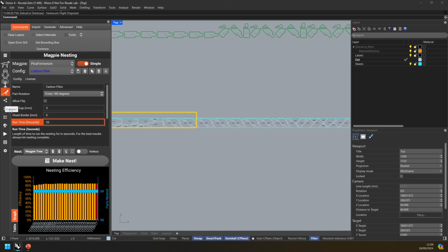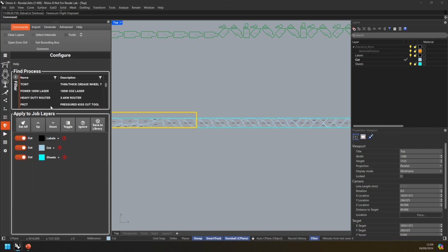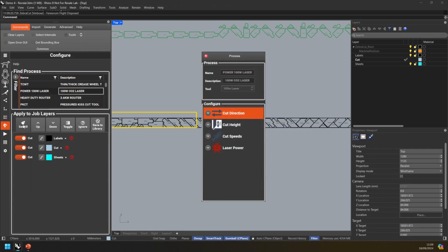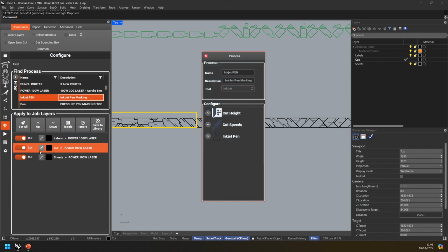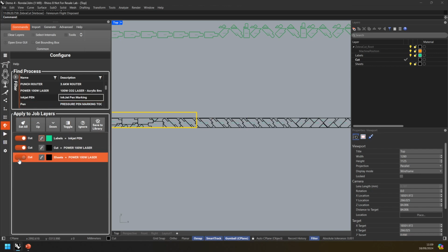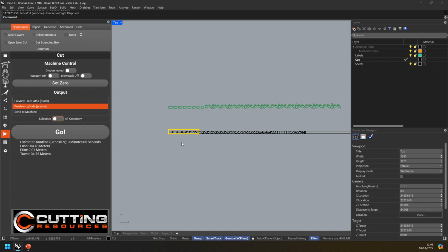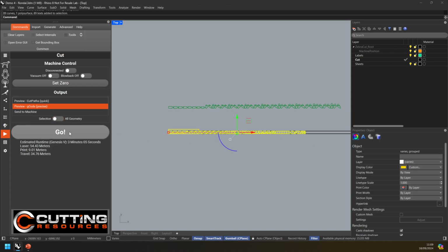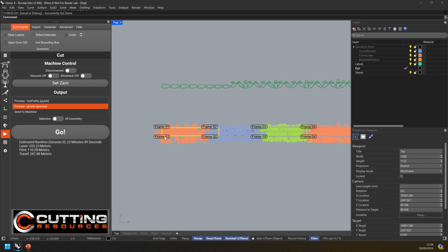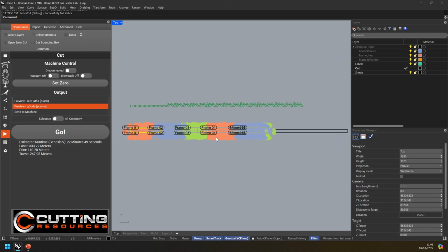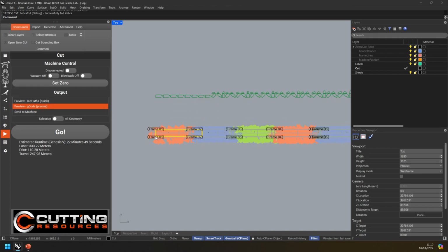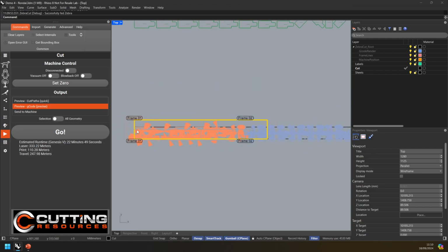Once that's done, we can then go and assign a tool. So let's laser cut everything, for example, just for purposes. Or we could go through and do inkjet marking on the labels. We don't want to cut the sheet, and then we'll preview selected geometry because we only want to do this part of the geometry. And we say go. And there we go. This is producing on the order of 100,000 G codes, and quite a few frames worth of geometry. So there we go. That is how we helped Rundle save themselves hours and hours of manual preparation of parts.